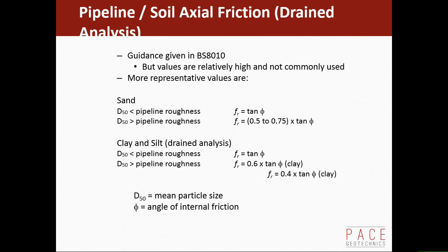Clay soils, most of the time it's going to be a smooth coating because clay is very fine, and therefore you're not getting the same level of interlock, so you'll be tending to use these sort of numbers here as a range.